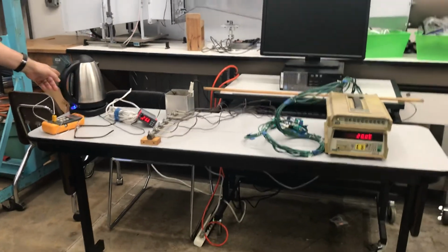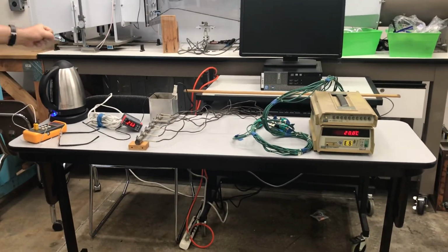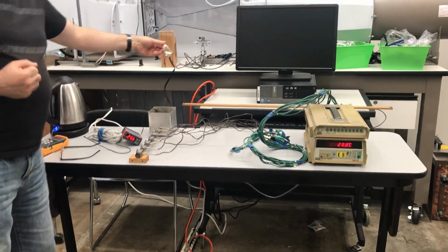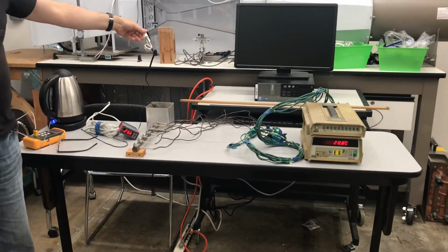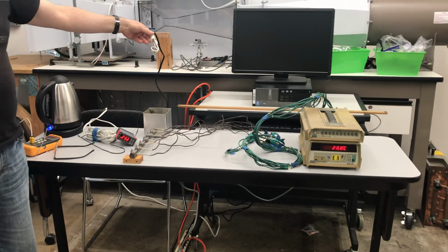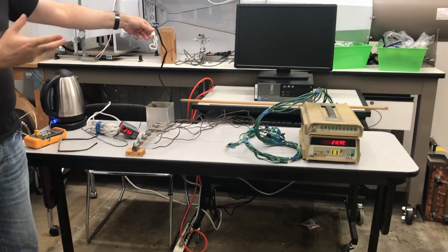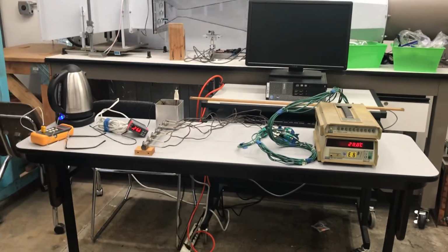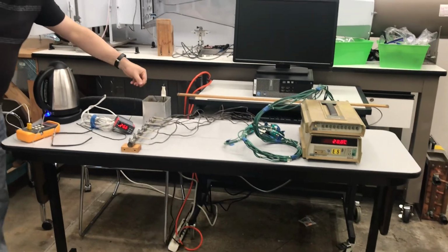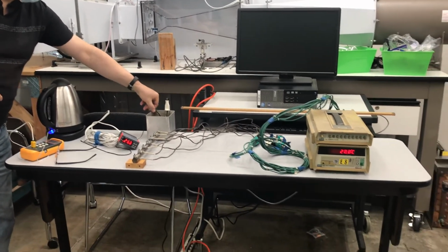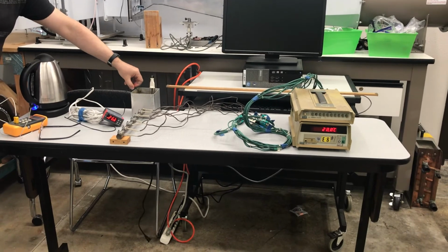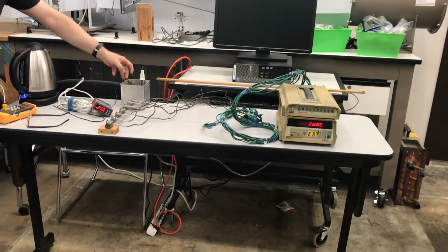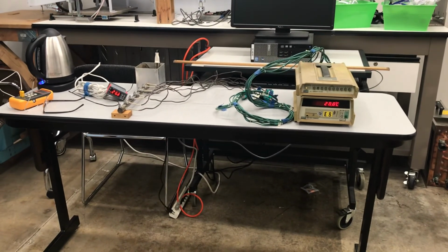Now, as soon as the temperature starts boiling, what we do is we pour it in here. This is the submersible heater that is connected to this temperature controller. So if the temperature goes below 98, it turns this on to add heat to the water to keep it at roughly the same temperature, right? So that's a heater, except that it does not provide heat constantly, right? As soon as we have a deficiency in temperature, it turns on.